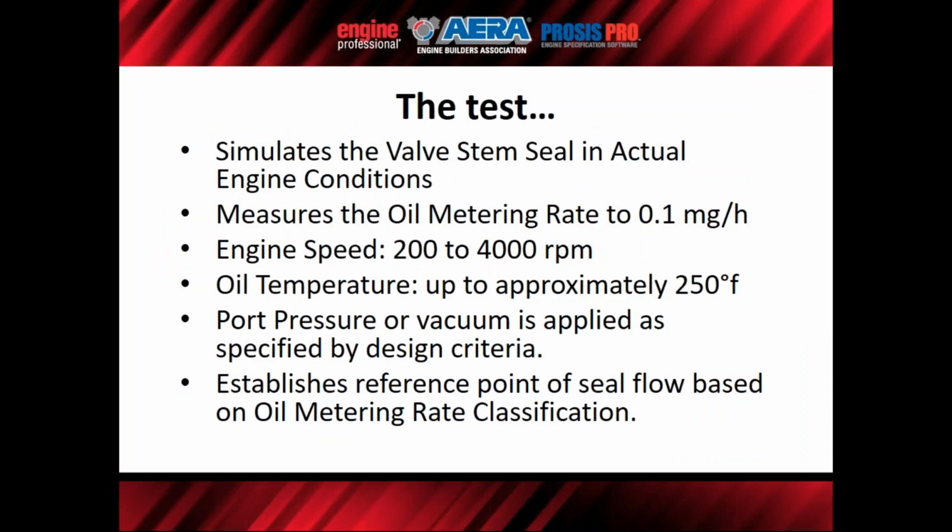So the test simulates the valve stem seal in actual engine conditions. Measurement of the oil metering rate is at 1/10 milligram per hour. Engine speed, these rigs will run, as you can see, from 200 to 4,000 RPM.